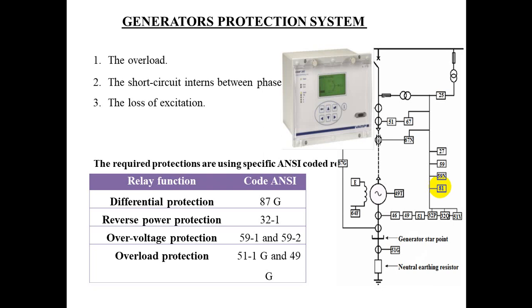In the former case, the earth fault relay is required to be graded with other fault relays in the system. This is the reason why an inverse time relay is used in this case. But in the latter case, the earth fault loop is restricted to the stator winding and primary winding of the transformer.